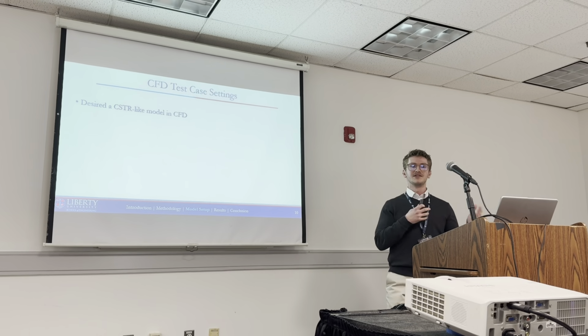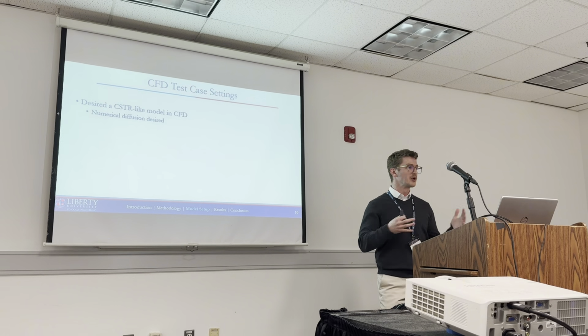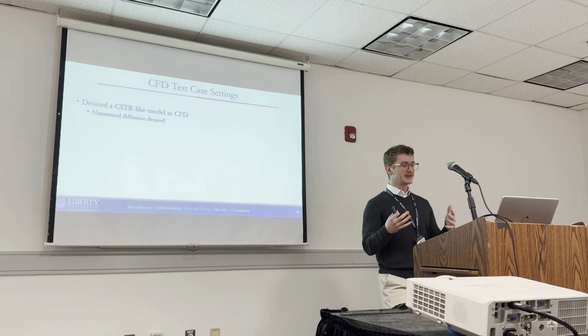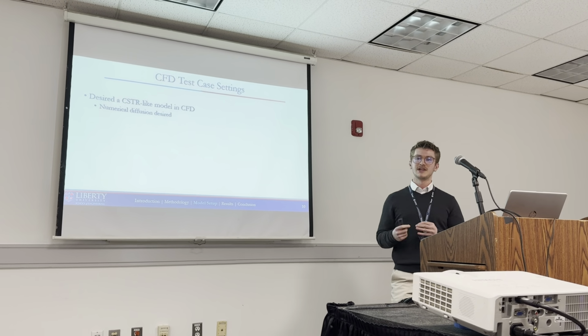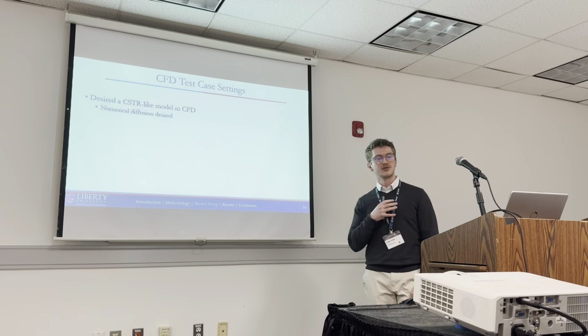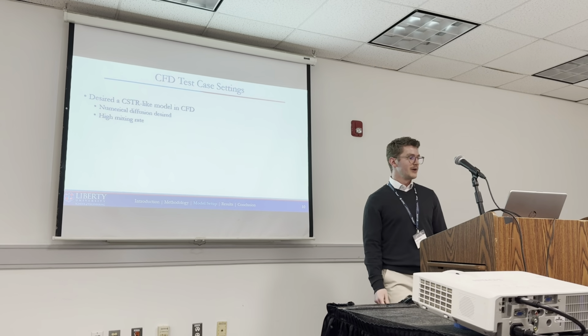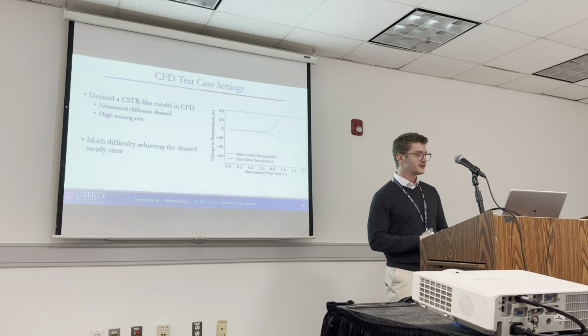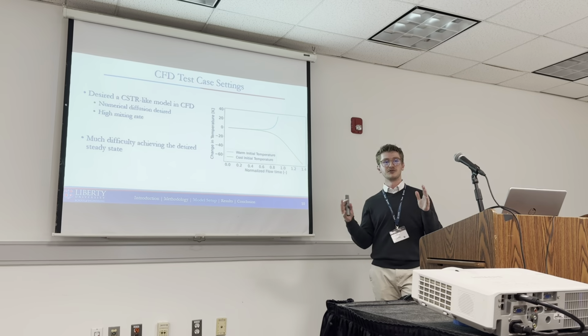So, as previously stated, we desired this CFD model to be like a CSTR, so we wanted it as perfectly mixed as we could. So in this case, numerical diffusion was desired. So we used large, coarse, tetrahedral cells, low-order discretization schemes, a K-epsilon turbulence model, things like that. We had a high mixing rate inside this reactor,